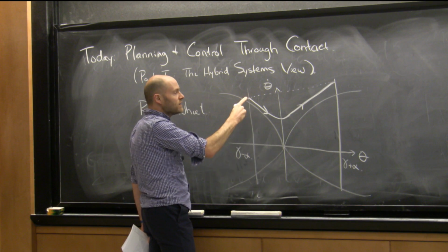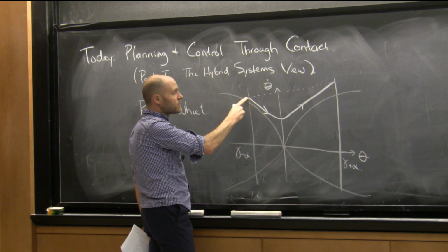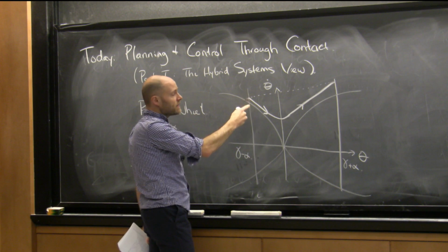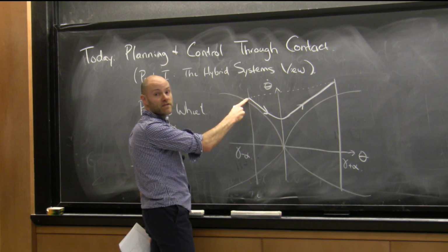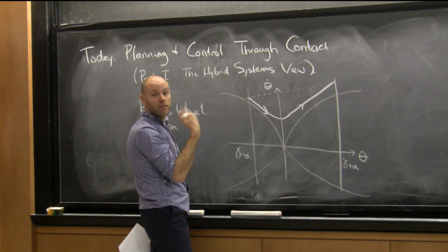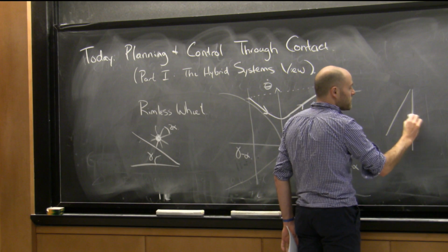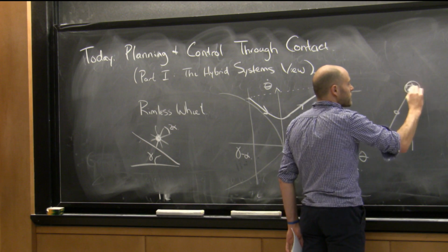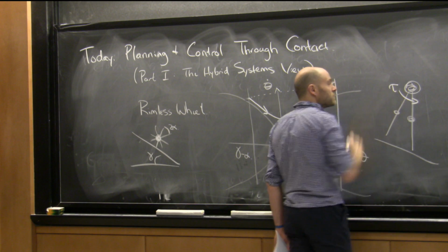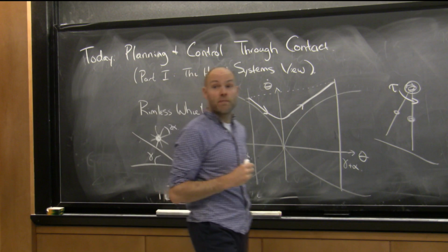But now that we understand how to do trajectory optimization on these systems, it turns out the more general approach to finding these limit cycles is with trajectory optimization. That's true even in the passive system, but the reason it's more powerful is that if I go to controlled systems, like the compass gait, I talked about as a passive walker, but the simplest control problem we have in walking robots is when you take that compass gait and you suddenly just add a torque at the hip, and you'd like to ask, what are the stable solutions of that where the torque may not be zero over time?